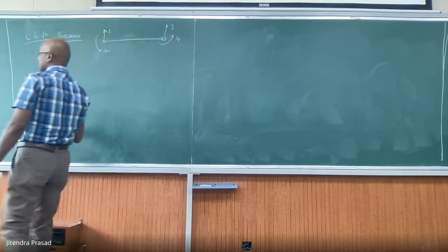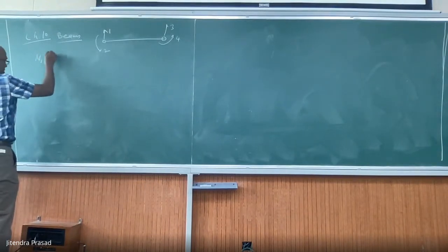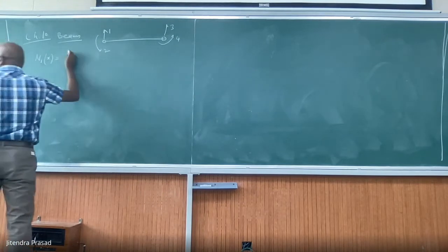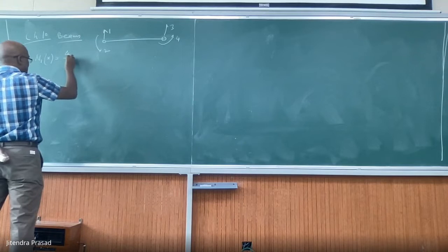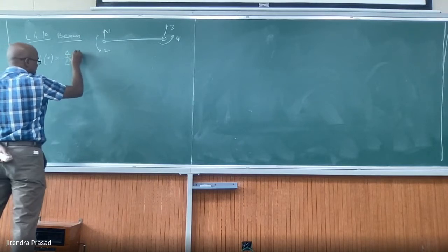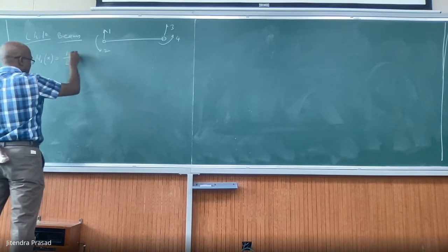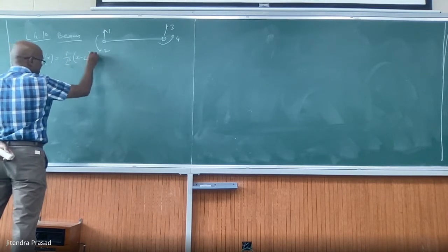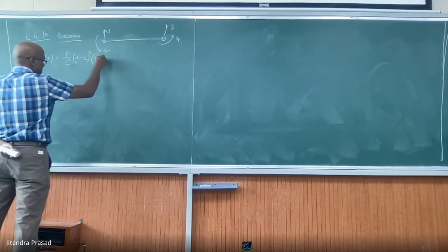Corresponding to that, we find N1(x). We found this as, what is the value, guys? 1 upon L cube, (x minus L) square, (2x plus L).